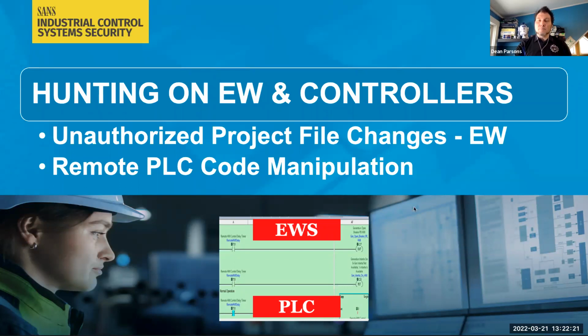And again, based on and modeled on threat intelligence and previously observed threats, we have seen the adversary control the HMI, update software, and update logic in the controller from the engineering workstation. So let's walk through this hypothesis, focusing on unauthorized project file changes from the engineering workstation, which ultimately leaves us with remote PLC code manipulation.